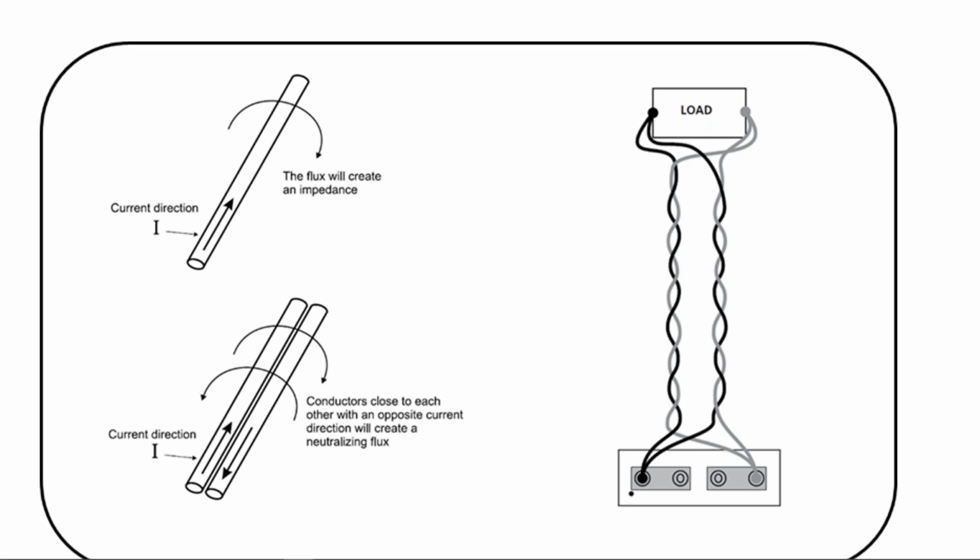I would say in 99% of the cases, our actual test cables are not color coded on each side, right? All of them will be the same color. So be mindful of this. You have to create these twisted pairs with cables, in technical terms, with the current direction opposed to each other.